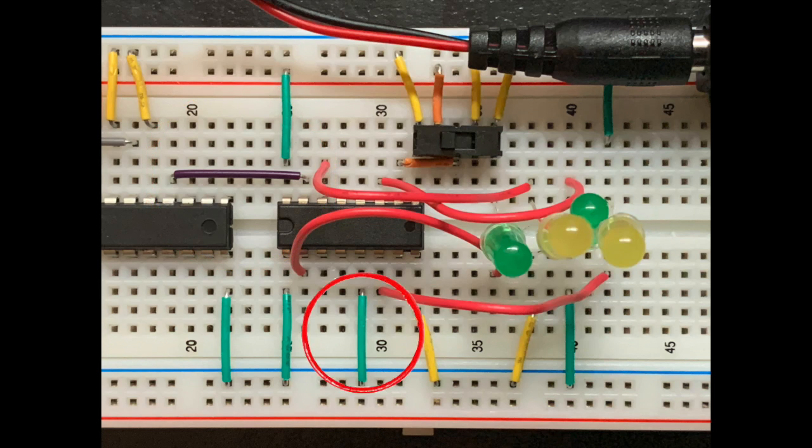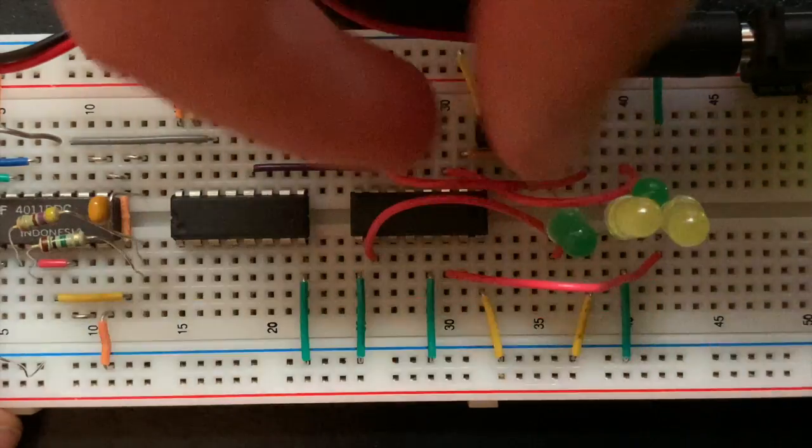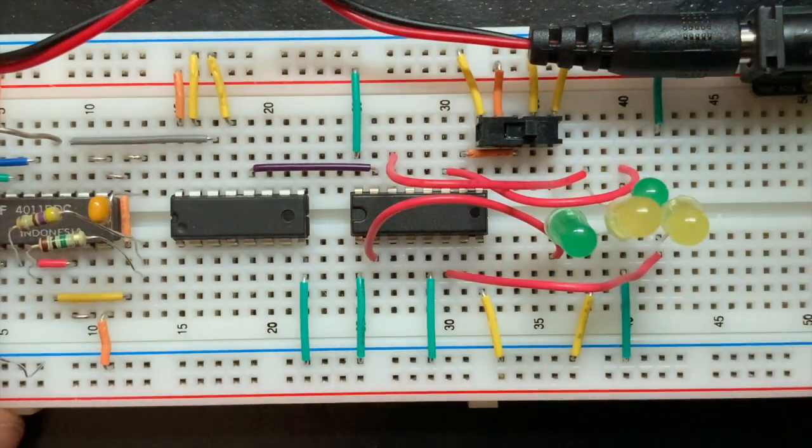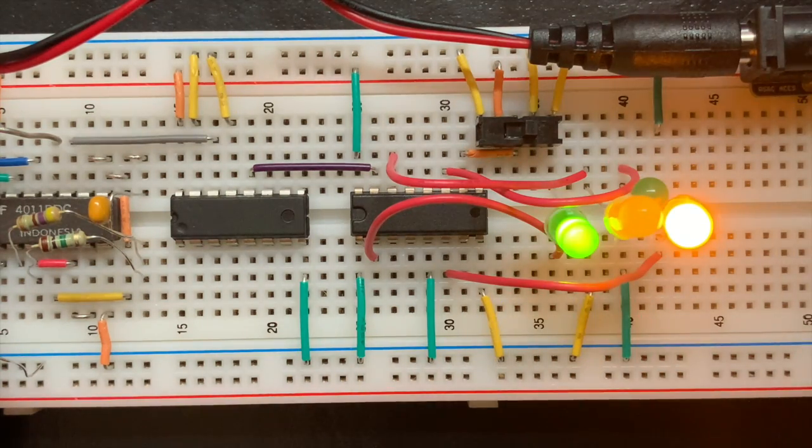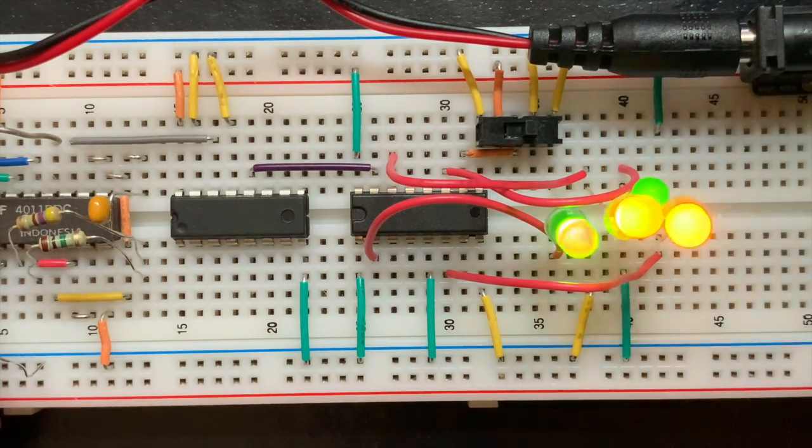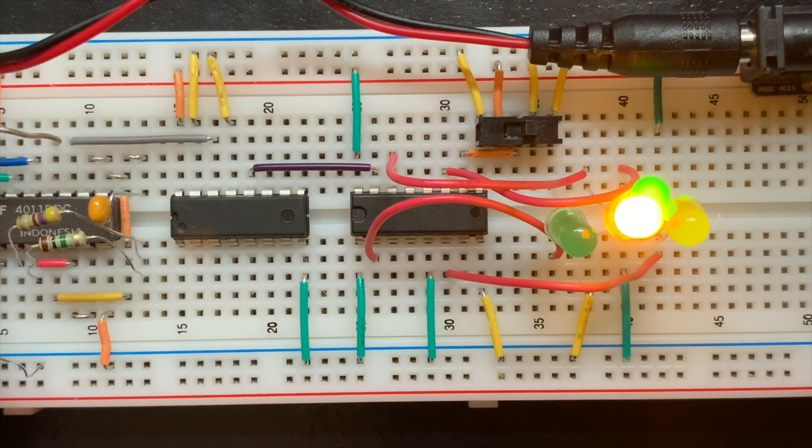Next, its carry-in, C1 pin, is grounded, and finally the up-down pin is wired to the SPDT slide switch, which when flipped allows the circuit to count backwards. Finally, the output pins are each wired to an LED as they represent a different binary digit. Here you can visualize this.